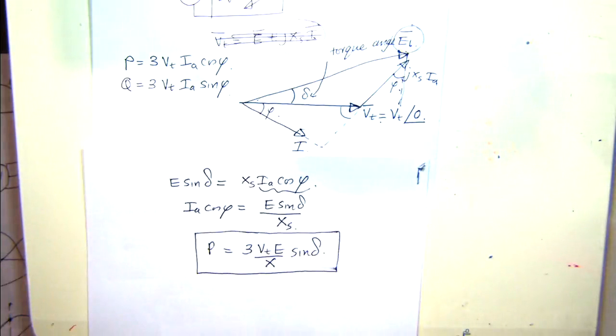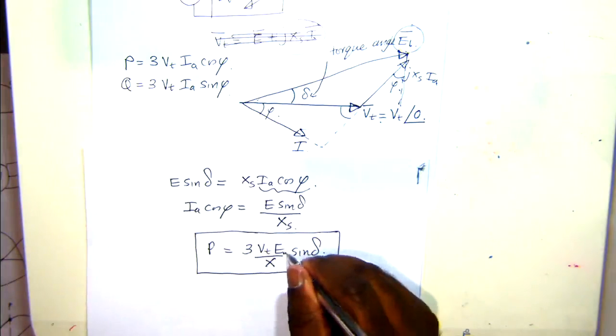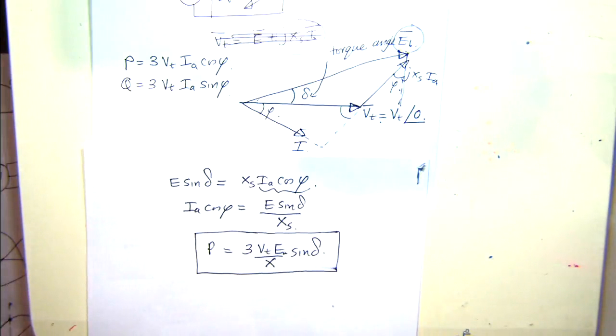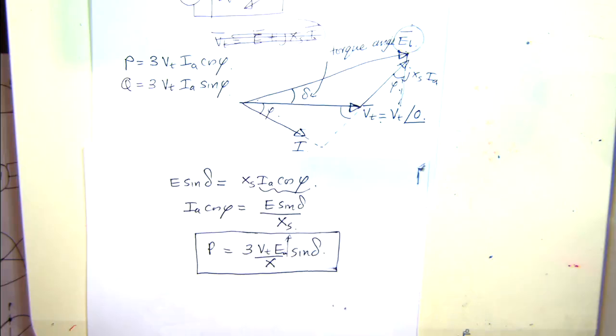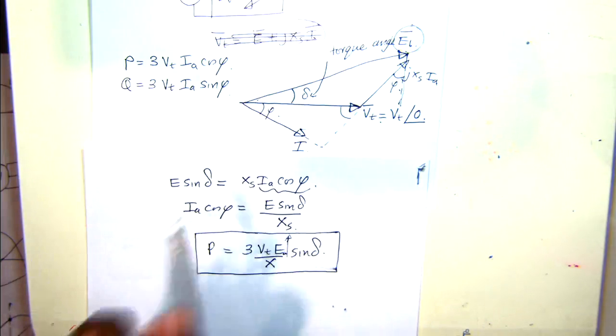This is a very important equation. You'll use this quite a lot in power system analysis. Let's say you change the field current, so your excitation voltage goes up. But your fuel input into the system is fixed, so the real power you're transferring to the grid is fixed.